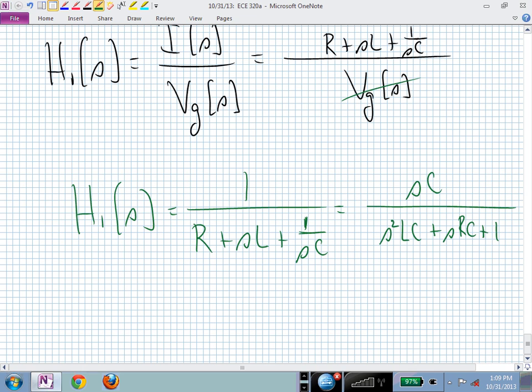If you have a capacitor and an inductor without any resistance, which in a real system you have some kind of dissipation, but if you don't have any resistance, now you have a pure oscillator. Now you know how to build an oscillator, and you know how to pick the frequency of that oscillator by the choice of L and C, your inductor and capacitor value, just by that second order circuit. So you could go into your interviewer and you could just keep going and going and going, right? You could even start sketching Bode plots after a few more lectures from this. Just a simple second order equation.